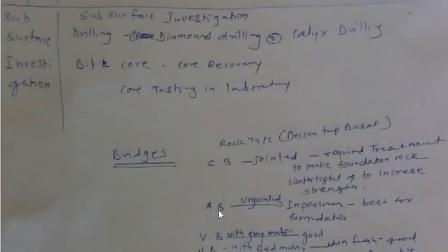There are a number of cases where the drilling was carried out, and at the time of design the engineer located the piers of the bridge according to his convenience. Therefore the foundation of a pier was taken away from the actual drill hole; the distance between the actual drill hole and the constructed pier was 9.5 meters, and you know the geology changes from feet to feet, and therefore there was a problem.